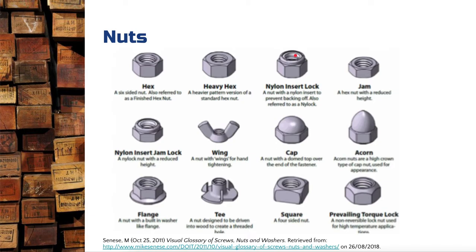Wing nuts, commonly used in applications where you might need to pull them apart, put them on and pull them off very regularly, and in applications where hand tightening is required. T-nuts, okay, very much used in knockdown fittings. These are actually hidden within the timber, so those little spikes there. Drill a hole, grip them into the timber, and then you have a nut essentially embedded into the timber. A few other options are available there, okay, but they're the main ones we talk about.